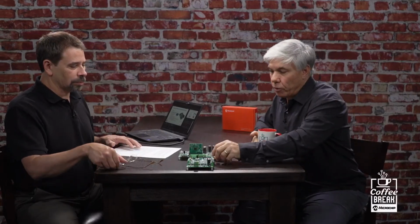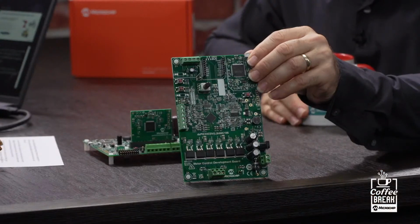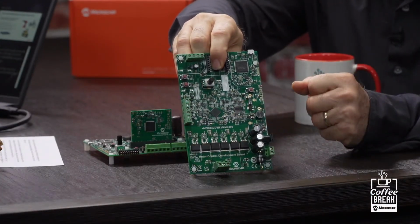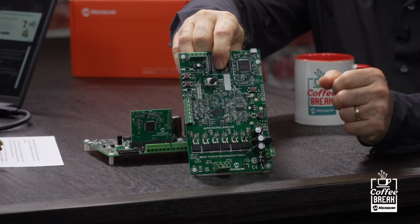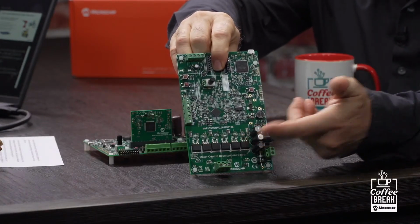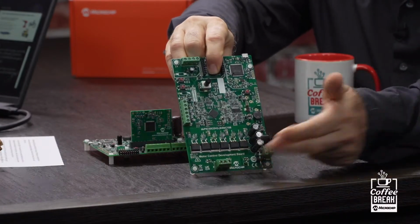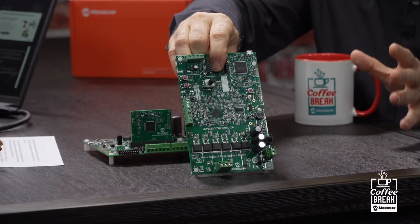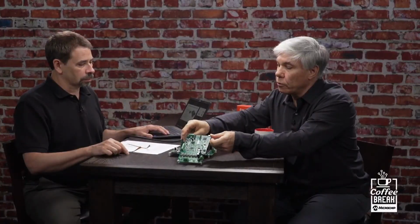I did bring a board here, and so this board is for our integrated motor drivers development. And in the middle right here, you can see the integrated motor driver, which combines the dsPIC digital signal controller doing the motor control job with the MOSFET gate drivers. And so there's really nothing between it and the MOSFETs at the bottom of the board here. So that directly drives the 6 MOSFETs, and then the connection to the motors at the bottom in the green connector. So this makes for a really clean, small board design. Okay. And this development board is what we provide to customers in order to do their development.